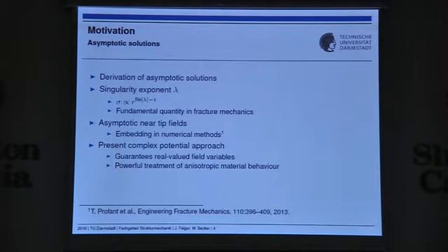Furthermore, the asymptotic near-tip fields allow for combination with numerical methods, and especially here for a very efficient calculation of the generalized stress intensity factors, which are necessary in fracture mechanics analysis.